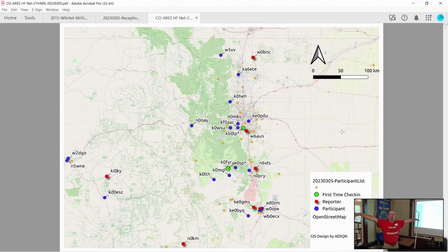You don't have to be perfectly flat top with a dipole. You can let it droop down a little bit. You can take any 2 bands that one's the multiple of the other, like 80 and 40, or 60 and 30, or 40 and 20, and you can put a central mast up. You can have one dipole coming down this way, inverted V, the other coming down this way from it, and you can have the feed points tied together on one coax.